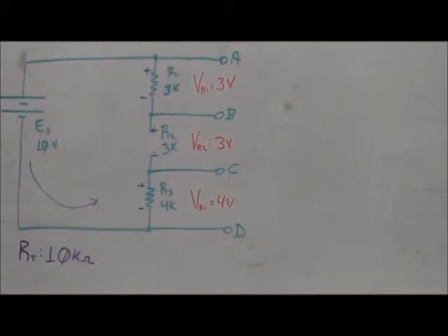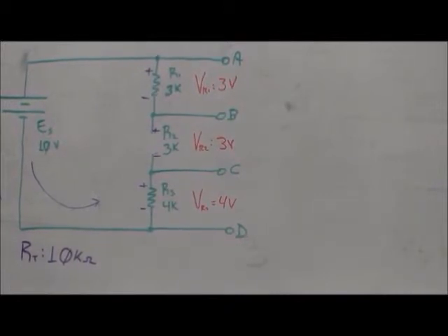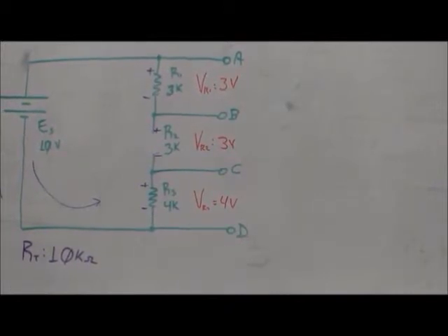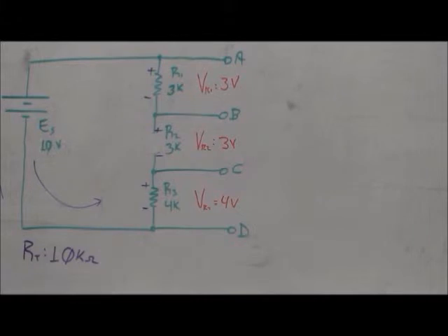Increase or decrease? Increase to what? Across R2, right? Because we go in series, we go to source at the point of an open. Okay, what about total resistance? It increases. I'm not going to say infinite, we're just going to say it increases. Okay? And what about total current? Decreases to 0. All right.